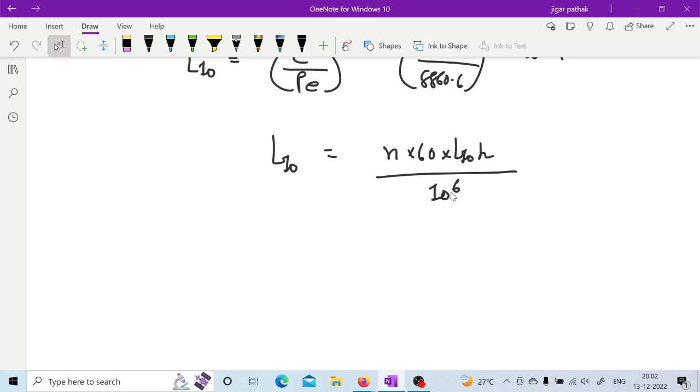What is the speed in the rating life formula, sir? N is given, I guess, right? That 575 we have calculated. The total revolution we have calculated as 575, and we have assumed a life of 1 minute, so 575 is your N here.